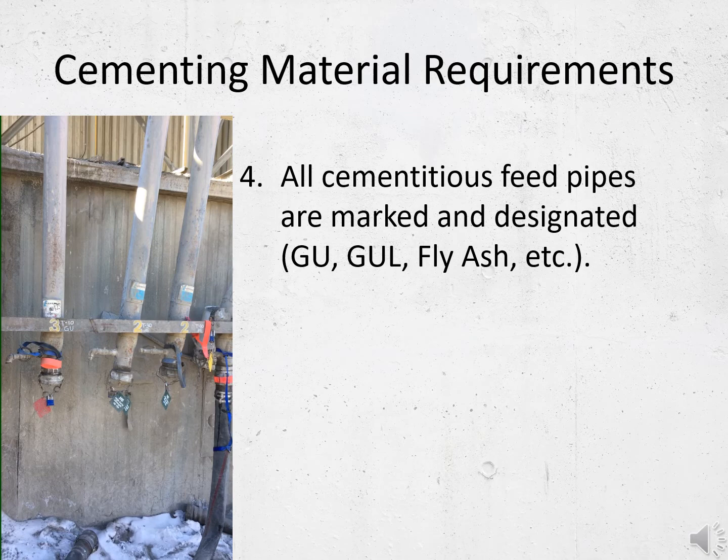Suppliers should have current reports on file at all times of the chemical and physical parameters, including strength activity indexes, of all fly ash sources used, as well as sulfate resistance and alkali-silica reaction mitigation minimum cement replacement rates for all combinations of cement and fly ashes used in production.